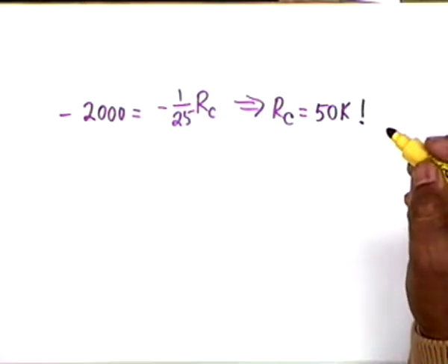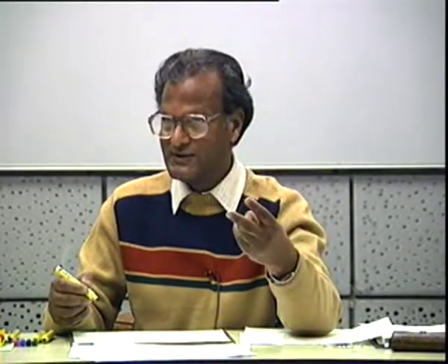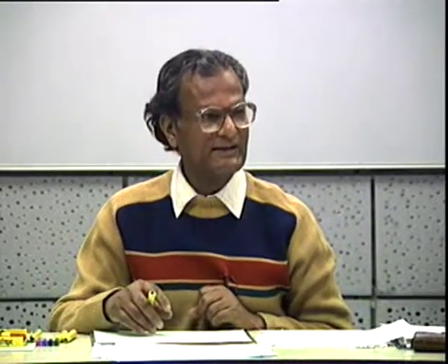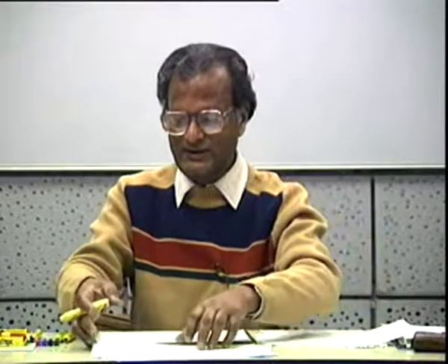So what can be achieved by a 50K resistance? I am achieving by 2 transistors and a resistance. I have a resistance R1. Now where does this resistance show its teeth? Because the gain is independent of R1. What does the resistance do? That sets what? The reference current, IR. Don't you see that?